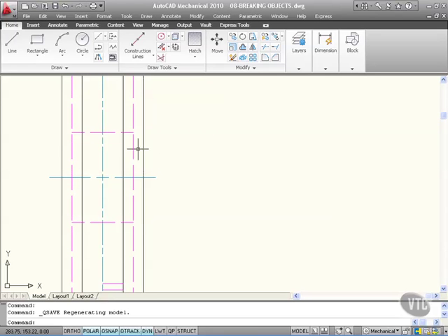And what they're showing is the indent on the outer edge of the belt wheel. Now, there is actually a hole for the central shaft to go through, but at the moment it's blocked. And we need to break this line here and this line here between the intersection there, intersection there, intersection there, and intersection there. Now, you could just use trim, but I want to show you how to use break. Trim would work just as well. Again, 2, 3, maybe 4 ways to skin a cat when you use AutoCAD.